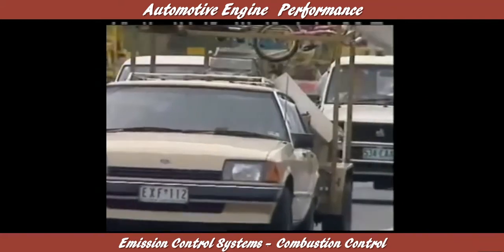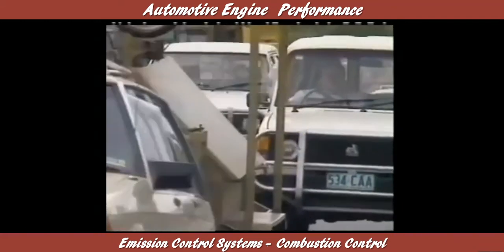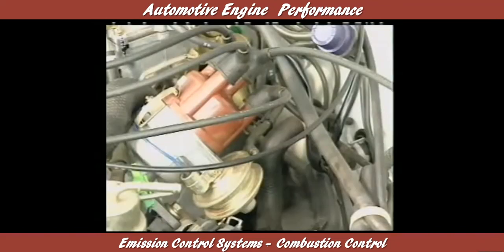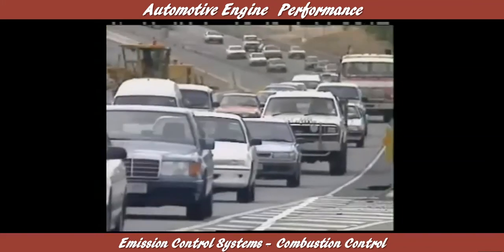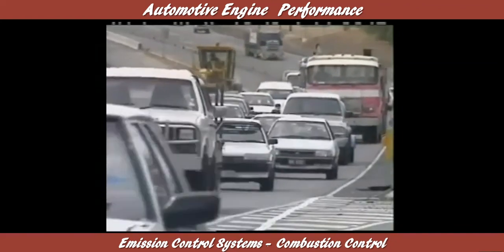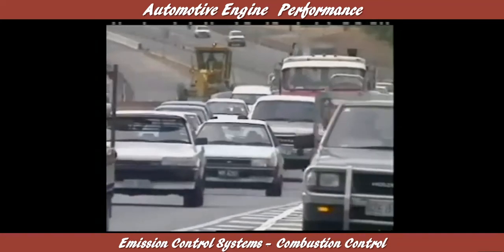Spark control systems use ignition timing to optimize engine output and fuel consumption with minimal emissions. They control vacuum levels to the vacuum advance unit on the distributor. In some designs, vacuum signals are delayed with vacuum valves in the signal line. In other designs, the vacuum signals are sustained. The signals can also be applied to dual diaphragm advance units on some distributors. The degree of control needed depends on many other factors, and each application should be considered individually.